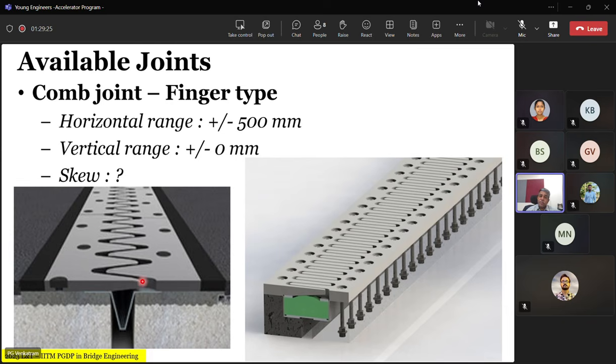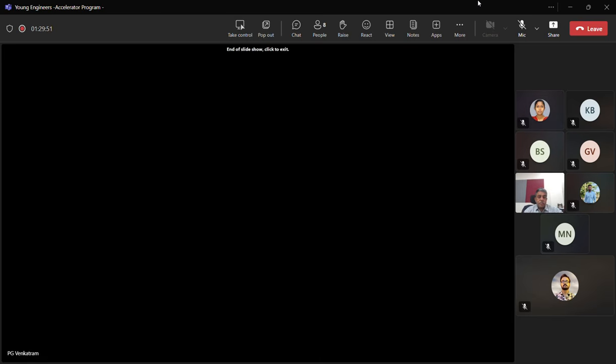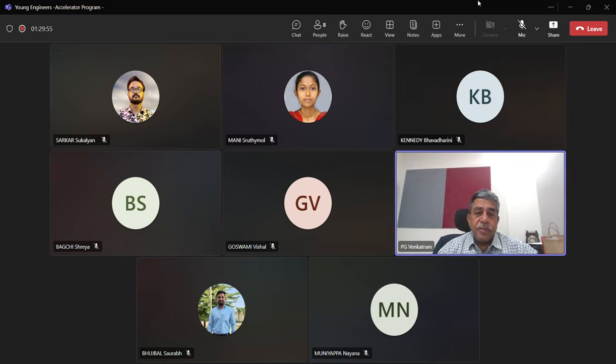And this is suitable for very, very large movements, but it has another maintenance issue due to vibratory and moving loads. The chances are the bolt anchors at the top get periodically loosened, so they start coming out. So the maintenance regime must go back and retighten all of them at periodic intervals to make sure that this joint works properly. So that's the last of it.